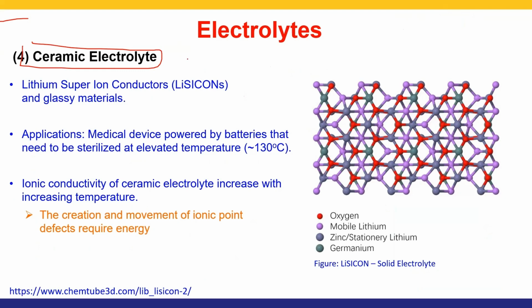The ionic conductivity is very low at room temperature, and hence ceramic electrolytes tend to be used in high temperature applications. This type of electrolyte is proposed for the next generation electric car, mainly because of the excellent safety performance that can enhance customer confidence. Using the ceramic electrolyte, we can avoid leakage of the electrolyte and there are no fire hazards.